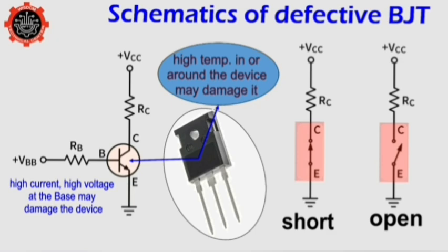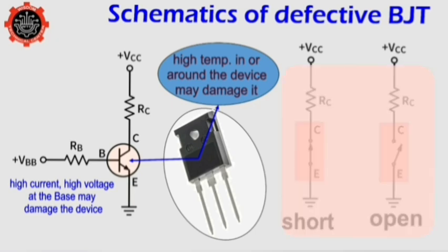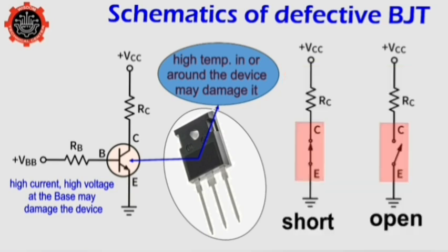Generally speaking, when a transistor is defective, it's either going to be open or short, which is pretty easy to find with nothing more than a digital multimeter. And also note that a transistor's characteristics may also alter enough to affect its operation. So this will not be pleasant, because what it will do is manifest itself as some unusual symptoms.